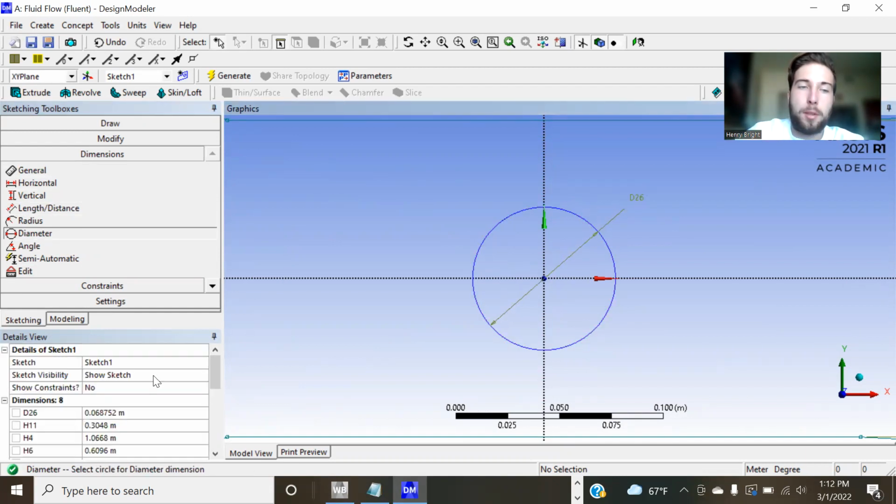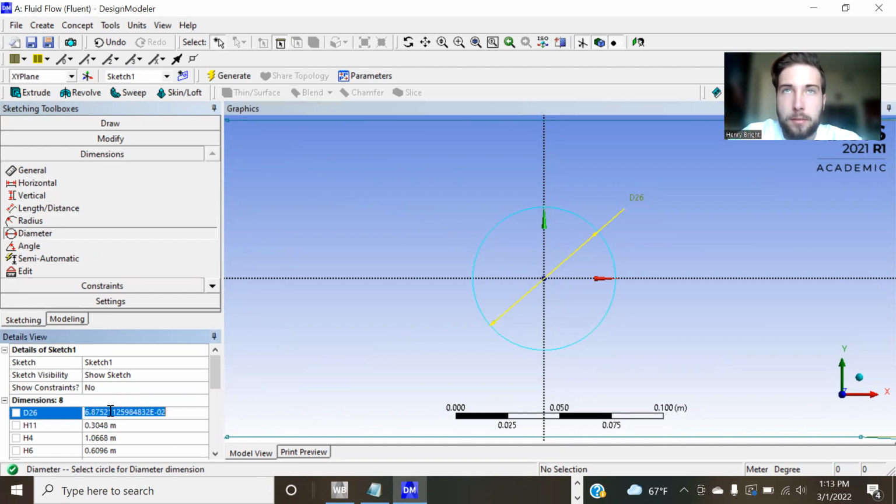Back to what I said about blockage effects, we need to make sure that in 3 dimensions the frontal cross-sectional area of this object divided by the cross-sectional area of the wind tunnel is no more than 10%. Sometimes it was 7.5%. I used 10 for this project just to make the object slightly bigger. So there might be a little bit of blockage effects if my ratio is a little off, but that's the number I've been going with, somewhere around that.